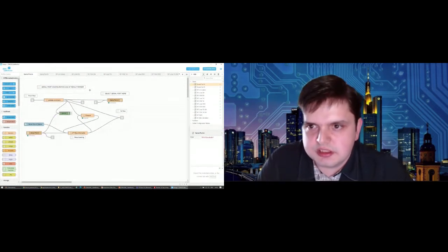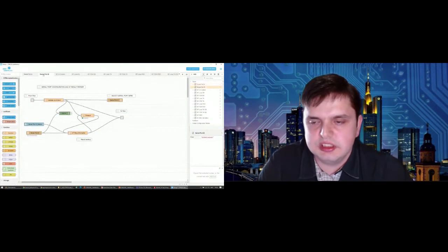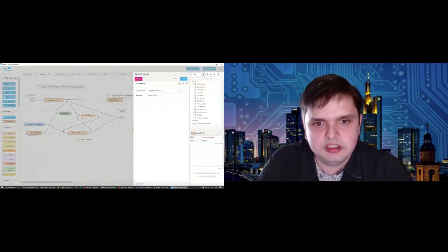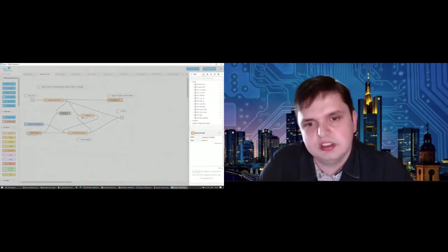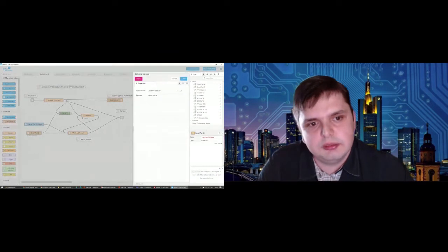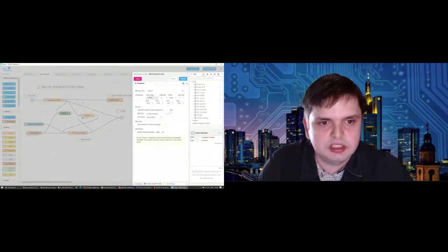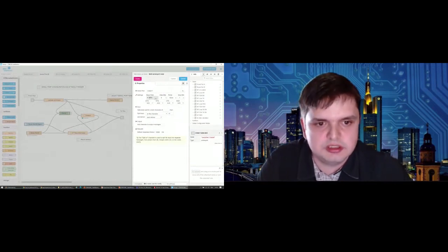Now, with a fresh installation, after loading the flow, I also need to set the serial ports, and that means opening these blocks by double click, editing, and creating a COM port with the required parameters.